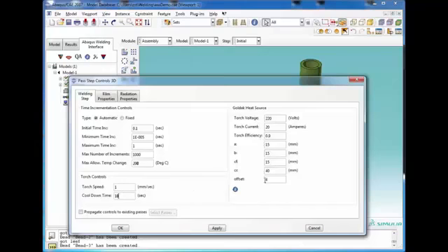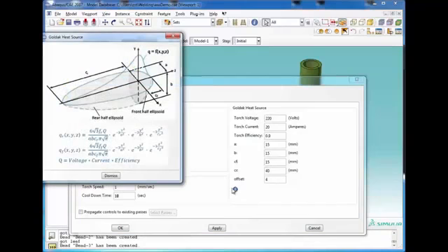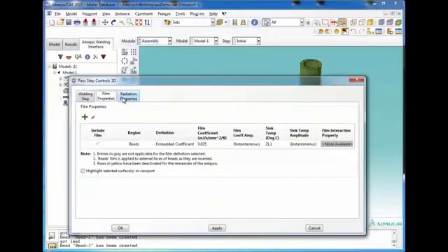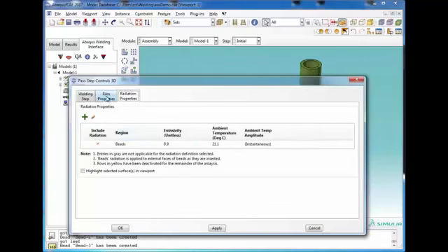And then here are the Goldak parameters. This defines our torch, and essentially we're defining all of these geometry constants of the shape of the torch. And now the other tabs here are for defining film and radiation loads. So the first line is the default, which is defining a film coefficient on the evolving beads. As the elements are being laid down, the exterior surface, which can have the heat radiated and convected, is evolving over time. So this first line is just to define the film coefficients, and then if we're doing radiation, we can do the same thing.